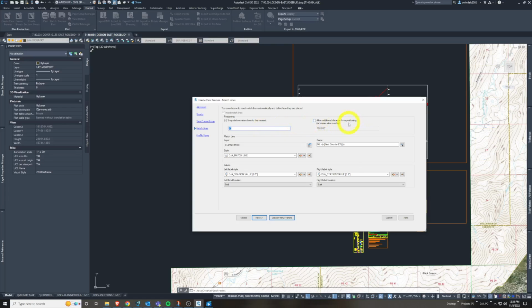This is additional overlapping between the beginning and end from profile view to profile view, or sheet view to sheet view, which has a corresponding plan and profile view in this case. This is adding another 100. So they already kind of overlap. We've been finding this gives it additional overlap. I'm going to say 10 feet there. I'm going to even say 5 feet. I'm just going to go low on that because there's already overlap. This just goes a little more even.